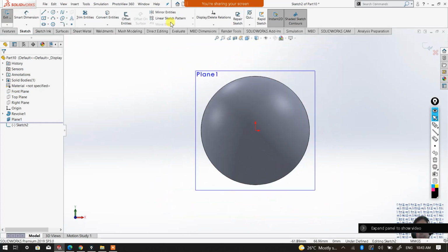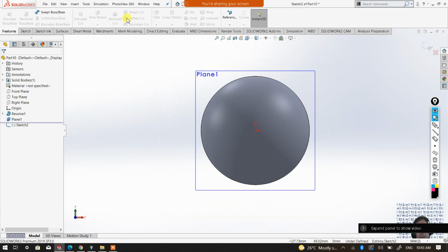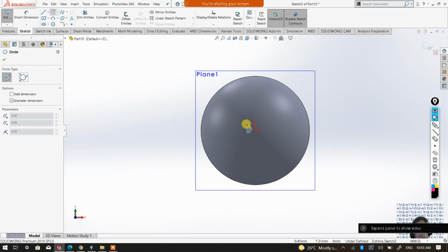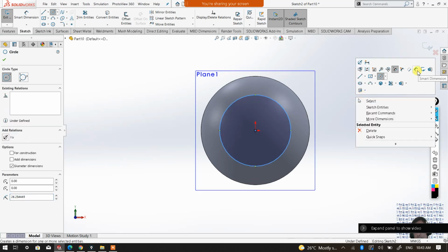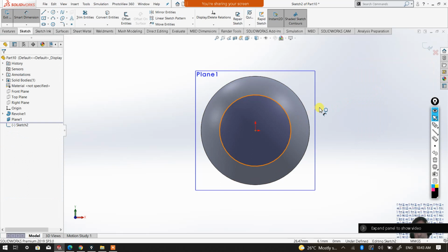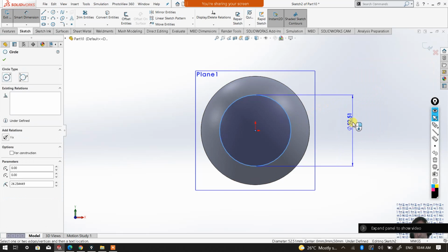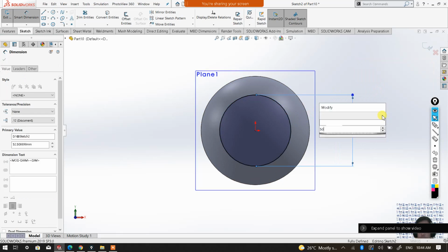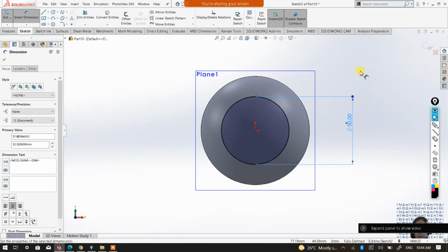I'm still going to show the use of swept cut, but to get to the swept cut, we need to apply all these kinds of activities. Okay, so still under sketch. Let's see. I'm going to create a circle here, around here is enough, but I still need to indicate the dimensions. Let's say the diameter of this circle is 50 mm. Okay, 50 mm. There you are.